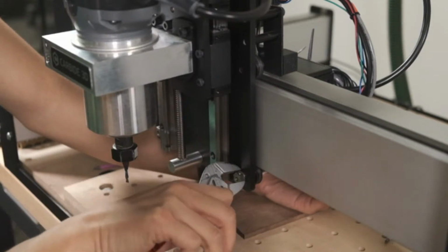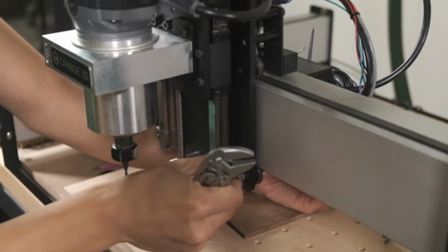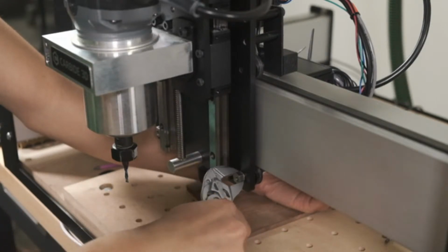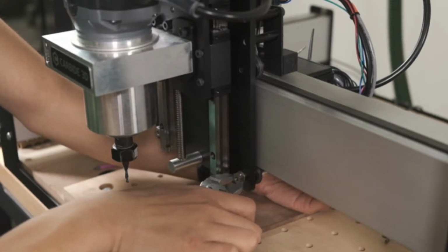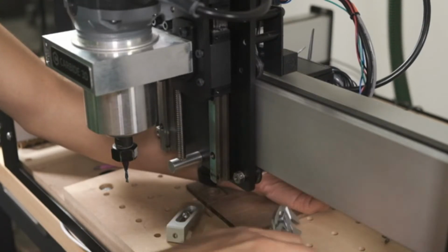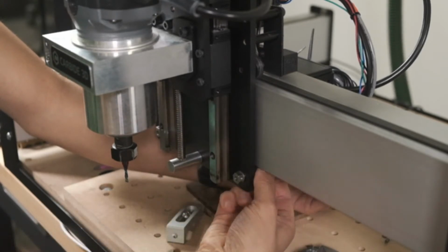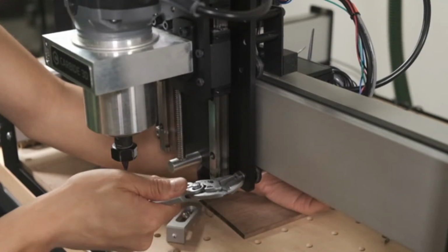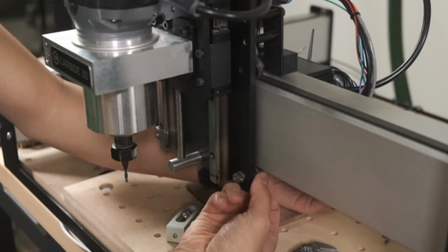If you rotate this counterclockwise, you can actually loosen the bolt holding this wheel on. So I always recommend going clockwise. So I'm going to bring this around. I can still rotate the wheel freely, so I'm going to keep turning this. And even less than an eighth turn increments is usually fine to get this close enough. This is pretty close to where I want this to be.